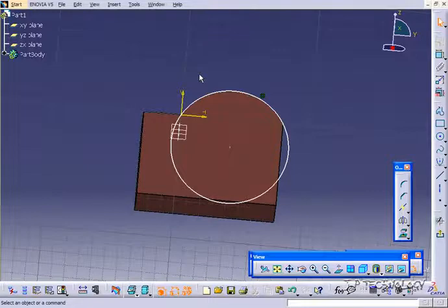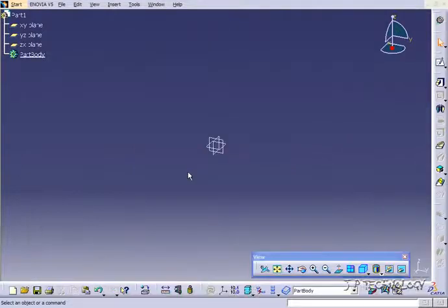When you're doing your drawings and creating your sketches, you're going to run into issues like these a lot of times, because you're going to have a sketch that you've made, but say an edge that you projected is behind it, and there's no way of getting to it without deleting that one that you just made. So without deleting it, you're able to hide it, delete the original projected edge, swap the space, and bring that drawing that you just made back. And that concludes our tutorial on how to utilize the visible space within CATIA V5.